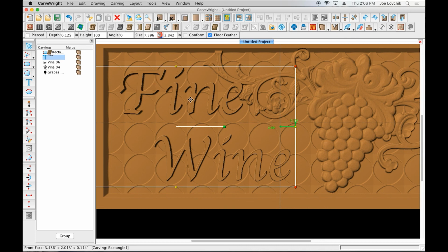And if you remember from the first tutorial, we talked about these straight up and down cliff edges, the bit will try to go and get that very bottom edge, and in doing so, because it's a tapered bit, it will chip out this top edge. And especially with text that's this thin, you will end up obliterating almost all the text, and then when you finish your carving, you're going to be very upset because your letters aren't readable and they're all chipped away.